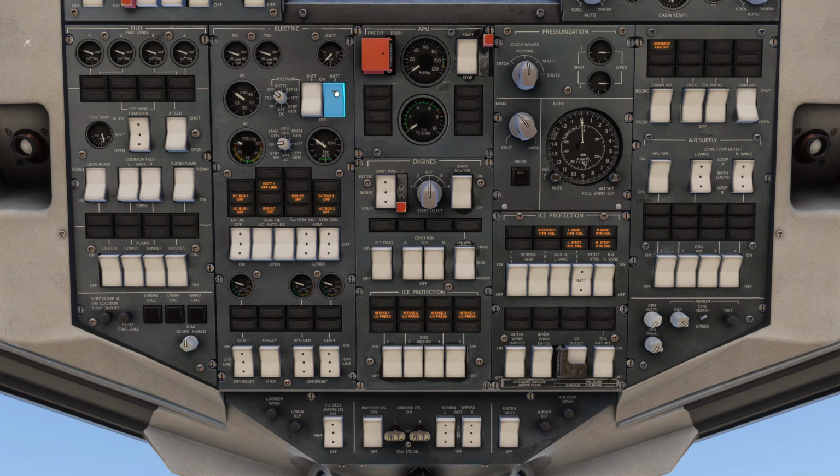Battery 1 on, battery 2 on. And I will check the voltage. Great, that's perfect. Let me know once the voltage is confirmed, and then we'll move on to the next item on the checklist. The voltage is below 28, so we have a problem. All right, understood. In that case, let's double check the battery connections and ensure everything is properly configured.